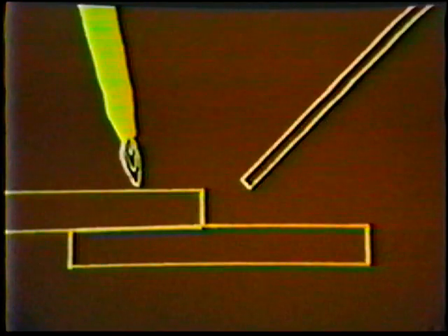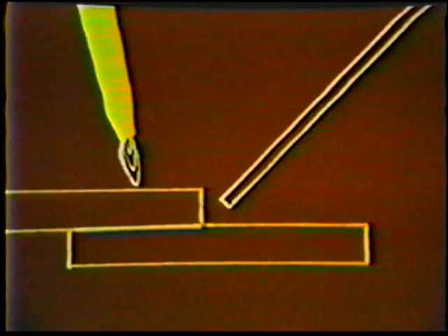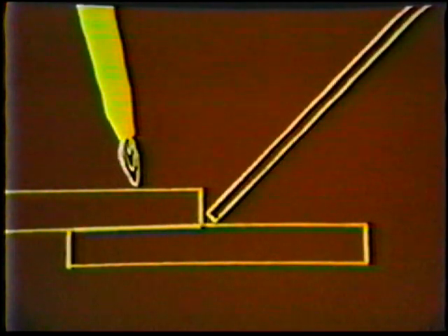Oxyacetylene brazing and soldering is also a thermal process. However, the base metal is not melted. It joins them by first heating to a suitable temperature, approximately 840 degrees Fahrenheit, and using a filler metal, which is melted and distributed between closely fitted surfaces to bond them together. The filler metal flows into the joint due to capillary attraction.